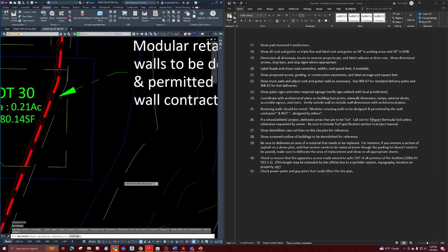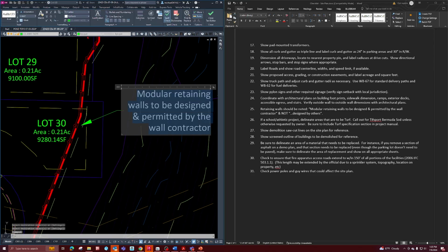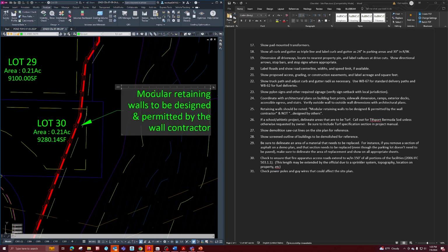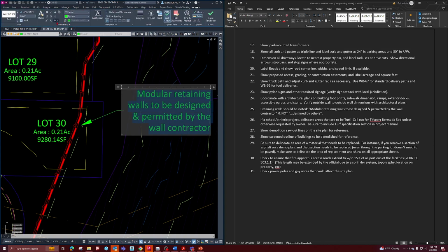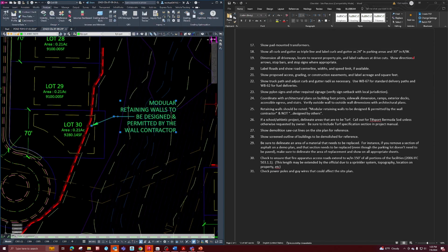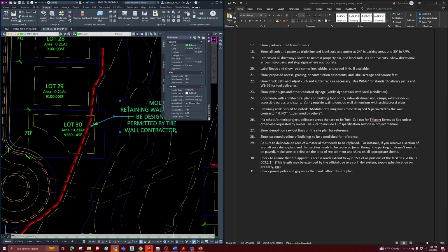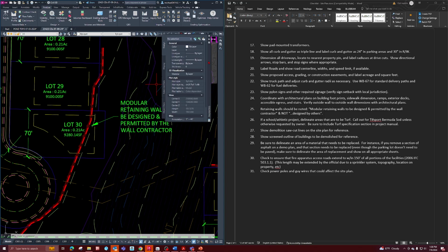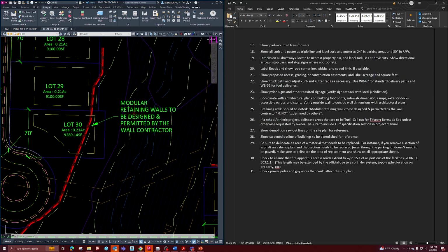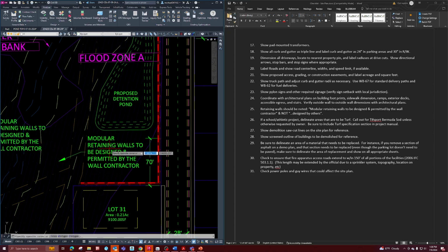I'm just matching the layer and the style. Since I copied it in from Word, it's associating it as a block for some reason. And then I'd want it to be capitalized, so I just go into here and change it to uppercase. And I think it would look better if it was justified to the left, so I'll just go over to the Properties tab and change that left. And then you'd want to make sure to label each wall.